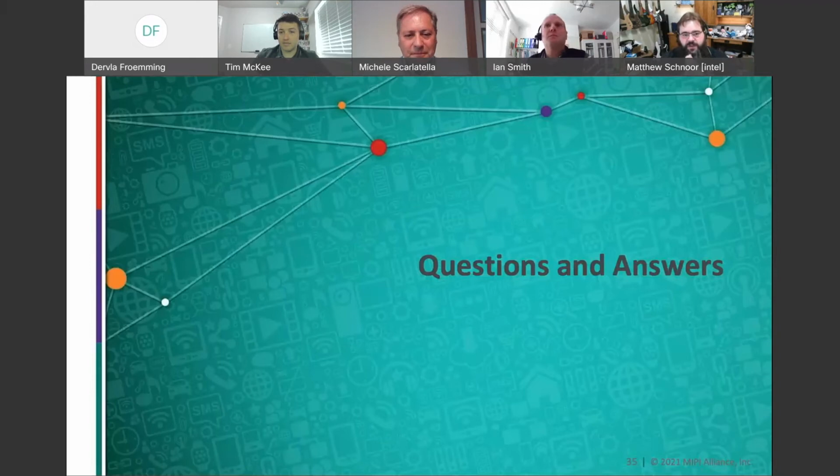What clock stalling is typically used for in I3C, we define clock stalling in specific places, and that's usually either to give the target device a chance to catch up or to allow an ACK/NACK time to propagate. I think Michele covered some of that. What we see for that is longer clock stalling, all the way up to the maximum in some cases.